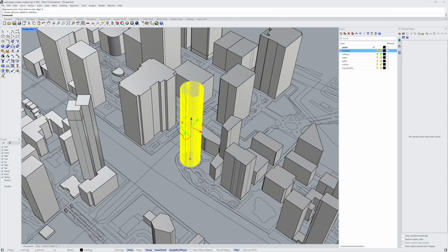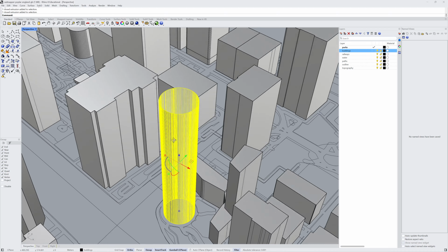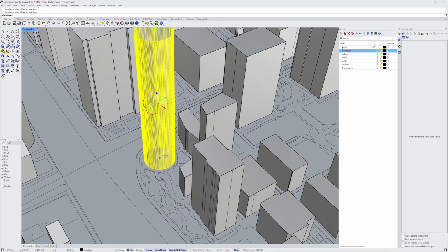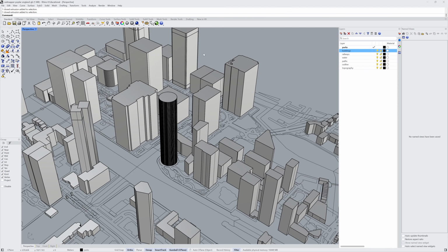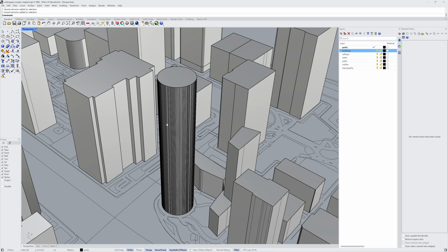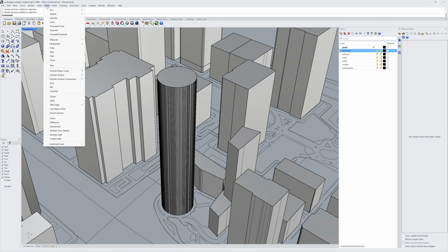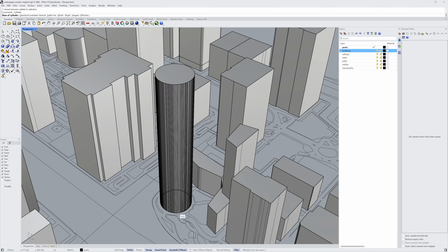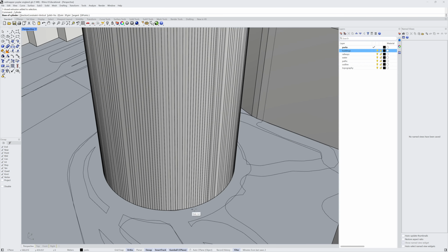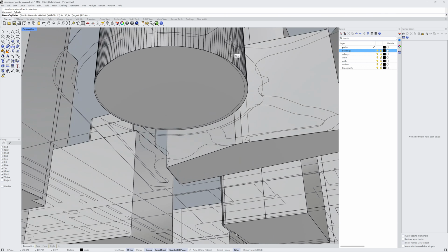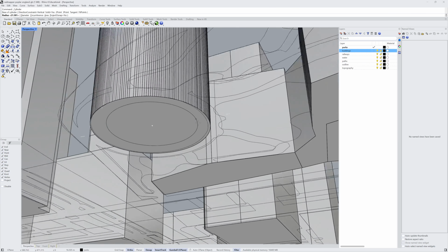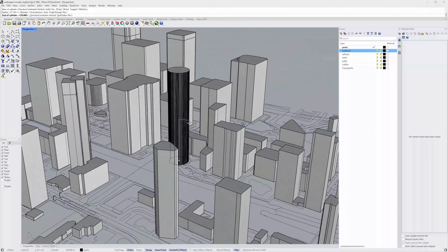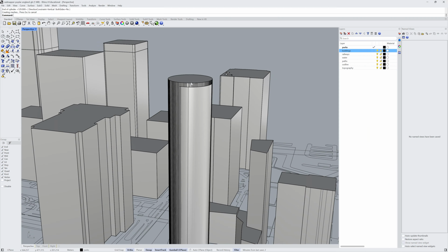Okay, now I'm just going to take this file. This is a closed extrusion, it says, and what it's done is extruded this line here. But I don't like how many lines this is giving me, so I'm just going to recreate a solid cylinder, and I'm just going to go to the center, if I can, of this object here. And if it's not allowing me to select, there we go, center. I'm going to get as close as I can to the original, and I'm just going to extrude this up. I'm just going to stop at the top there.